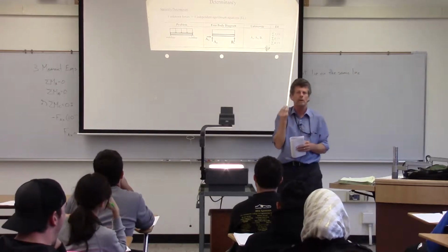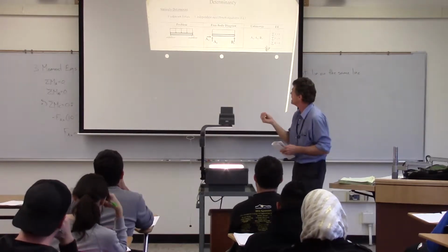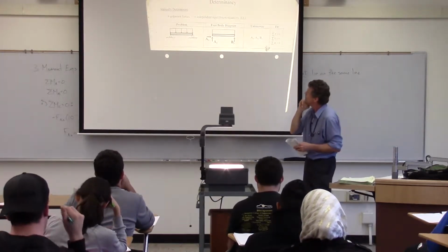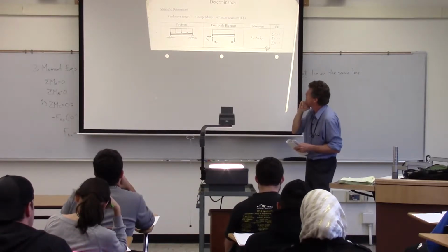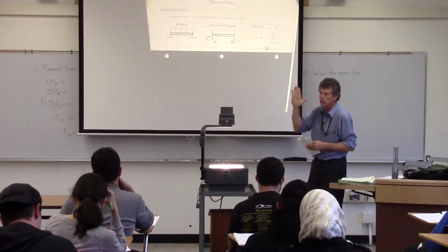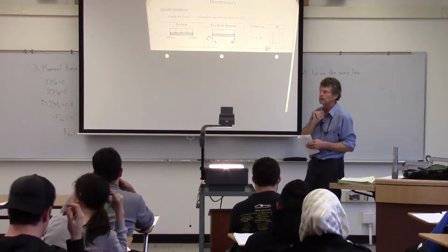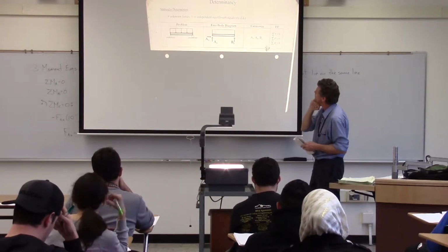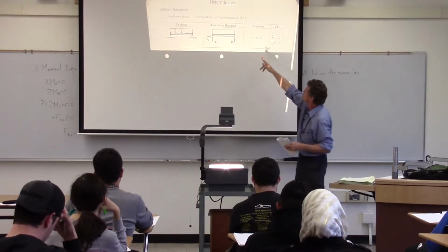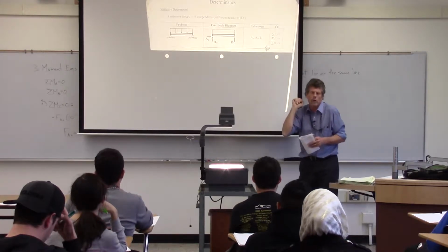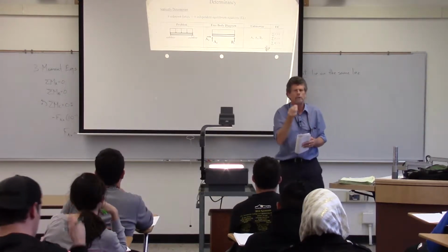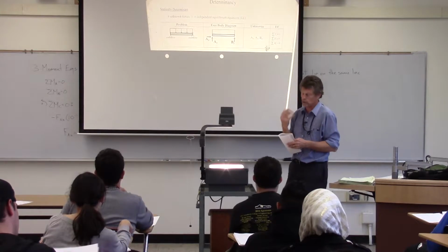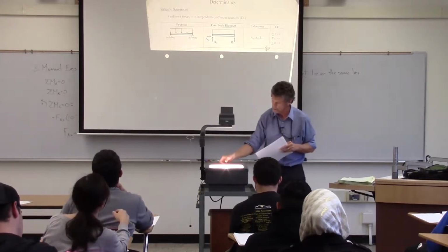What I have is 3 unknowns. I have my A in terms of force, magnitude and direction, and then the By, since I know its direction based upon that support condition that I pull away from it. So my unknowns are 3. I have 3 equilibrium equations. I can solve for everything there. I should be able to, unless I've really screwed up somehow.